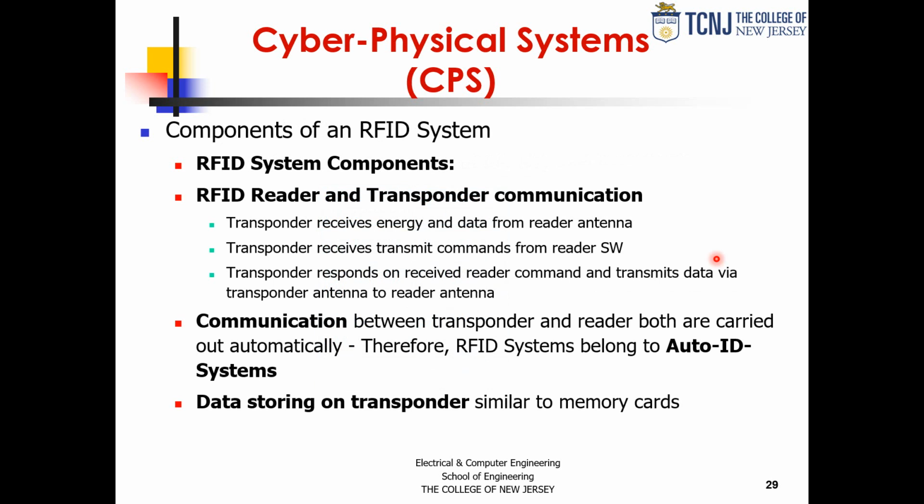So then, just to summarize, we have the components: processor, memory on the tag, an energy harvesting system, including a relatively big capacitor to store the charge and make the transaction possible. Then we have the reader, which sends energy in the form of RF, and after that it makes the query and it gets data.